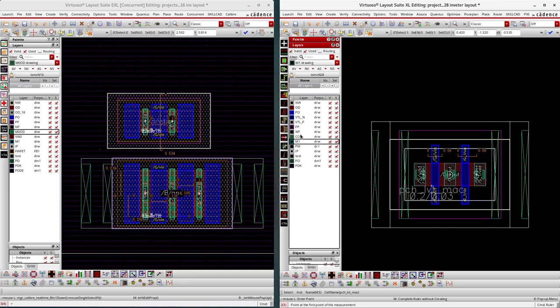Okay, so in here we used to call the layer called CO. CO is nothing but our contact which creates the contact between OD and M1. But when you come to the FinFET device, instead of using CO, they are using M0 OD. So M0 OD is nothing but our CO layer. The CO layer is our contact layer, which creates the contact between the base level layers. Base level layers are nothing but poly and OD. Okay, so instead of calling this a CO layer, in FinFET design they are calling this an M0 OD layer. That's all. No other differences are there.